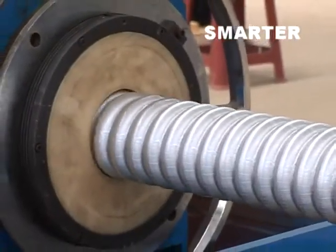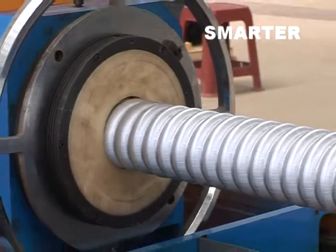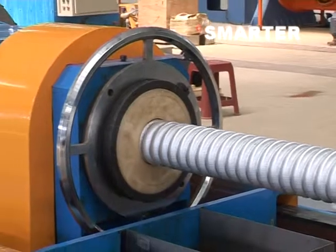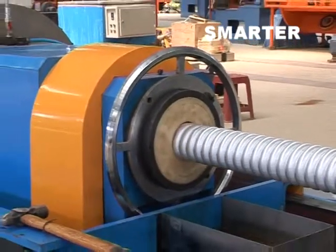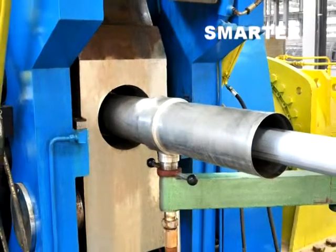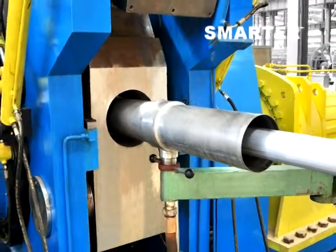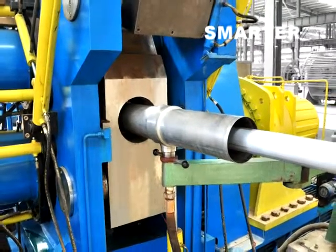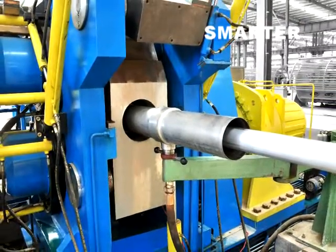Main characteristic of aluminum cladding continuous extrusion line is using up and down symmetric extruding wheel. Die block, die core, and die bush become symmetric extruding material passage. Aluminum rod goes into extruding cavity, which is formed by die core and die cover, then to become metal aluminum tube through even extruding pressure and speed at outlet of die.